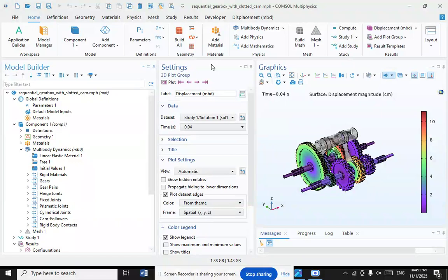The driver was therefore required to use careful timing and throttle manipulation when shifting, so the gears would be spinning at roughly the same speed when engaged. Otherwise, the teeth would refuse to mesh. This was difficult to achieve, so gear changes were often accompanied by grinding or crunching sounds, resulting in the gearbox being nicknamed a crash box.